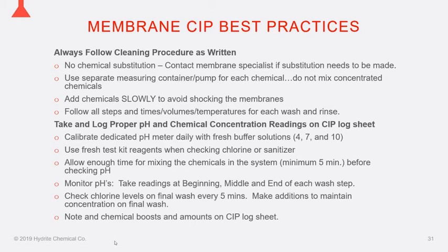And when you are adding chemicals to a system, the key is to add them slowly. We don't want a mass dosing into the feed balance tank or other balance tanks to cause a shock to the membranes. We want to get those chemicals added slowly so they have a chance to disperse and eliminate those very high or low pH shocks, depending on what you're putting in, okay?